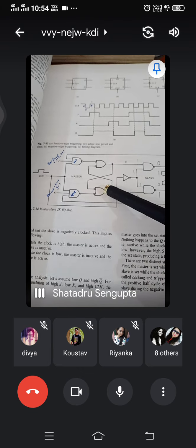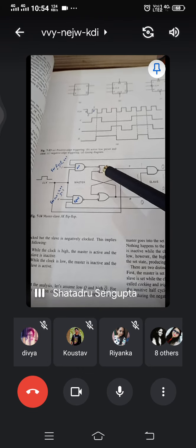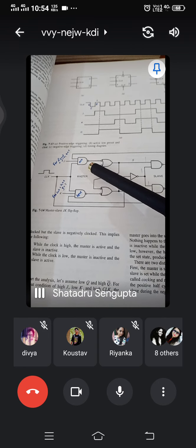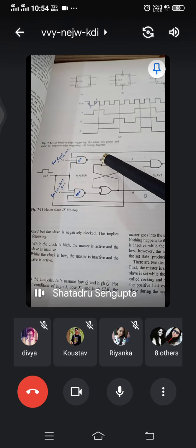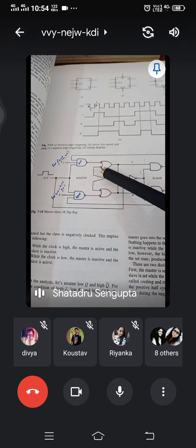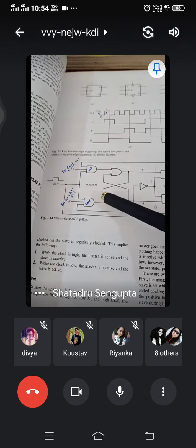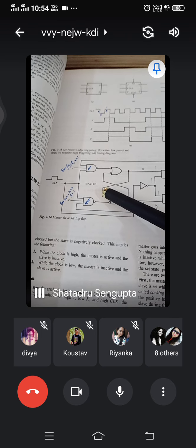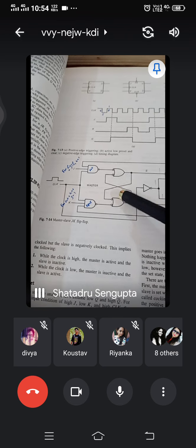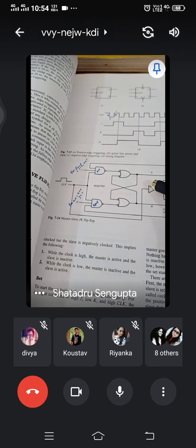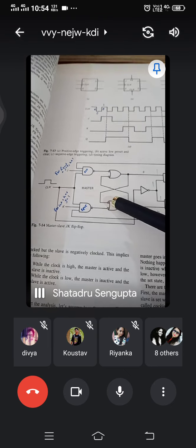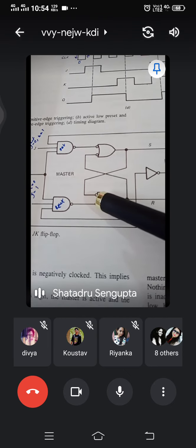As you can see, some diagrams I've shown you, including the ones that I drew, were with AND gates and NOR gates, but here they have used NAND gates and OR gates. It comes to the same thing. Also here they're inverting the signal to compensate for the NOR gates. So this tiny little dot here obviously means inverting it.